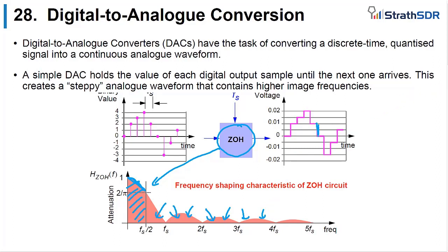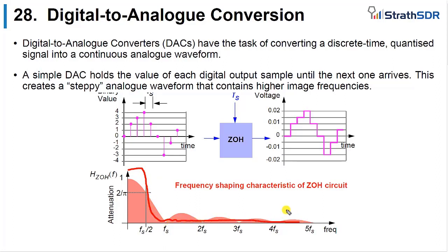So what I need to do is filter out those higher frequencies. I just need to get rid of these values up here. I also notice there's a bit of a droop here, so perhaps I need to compensate that with some sort of compensation filter. We often do that with a sin x over x correction. We'll review what that means for the RFSoC in a few moments.